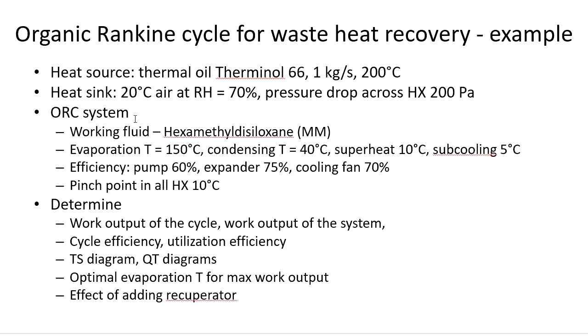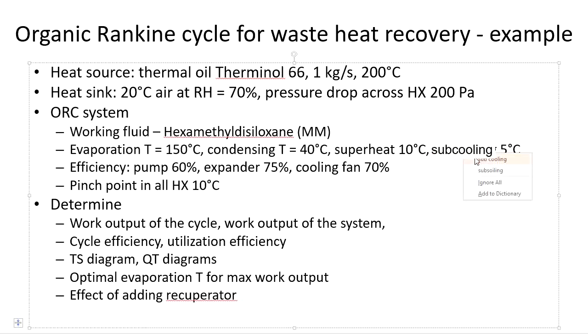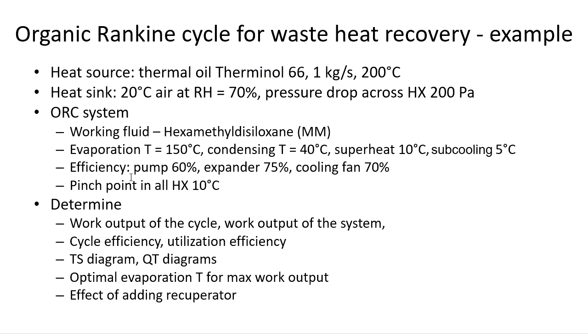Then the organic Rankine cycle itself will use MM as working fluid. Now we have given evaporation and condensing temperatures, superheat at the inlet of the expander and subcooling at the outlet of the condenser. We have given efficiency of the components, and the pinch point will be the same across all heat exchangers in the system, which will be 10 degrees C.